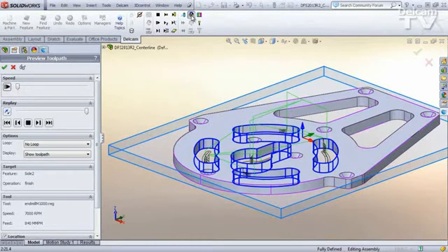You get a replay box and an options box. So I'll go through these one at a time. First, the replay box gives me the same little button here. I can single block through. I can go fast forward, take the toolpath in larger amounts. I can also go backward. So this is new. I can go backward through the toolpath. It actually erases the toolpath as it does so. And I can do that in a fast forward fashion as well.